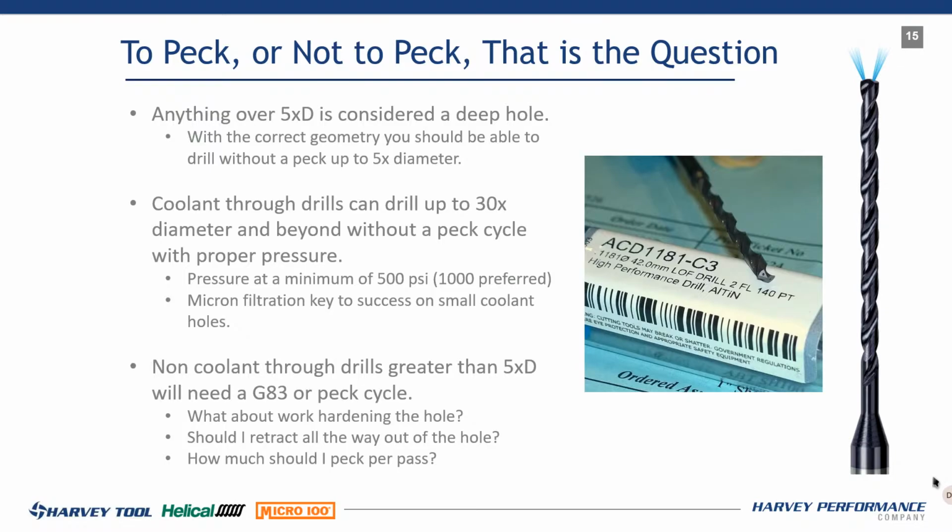Don't worry about work hardening the hole. What I see is you'll probably not get through the hole if you're going 8, 9, 10 times D, depending on the diameter. Now, this is a function of the diameter. When we start getting larger diameters, we have a little bit more room. We can manage the chip a little bit better. When we start getting down to that 1/4 inch and smaller, we really have to be mindful of this. So I'm telling you, between breaking a tool or breaking a chip, I'm going with breaking a chip. Think about it that way.